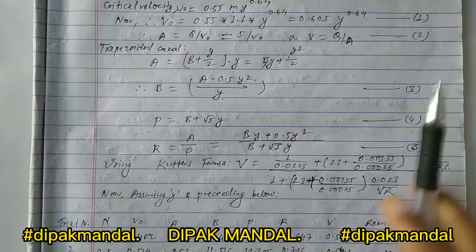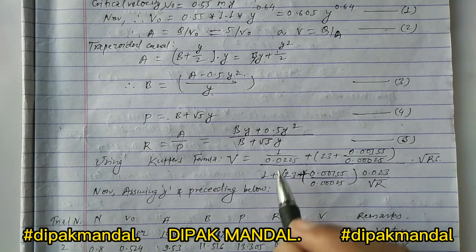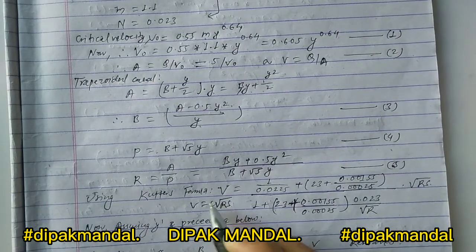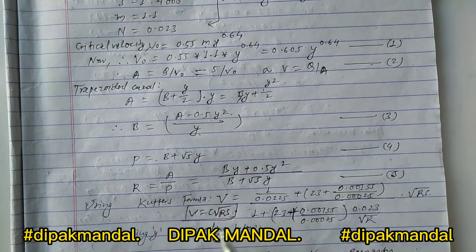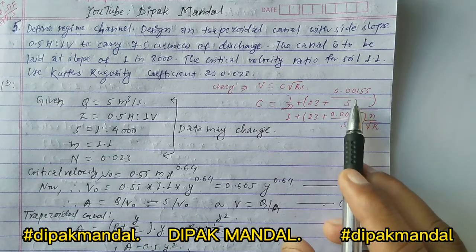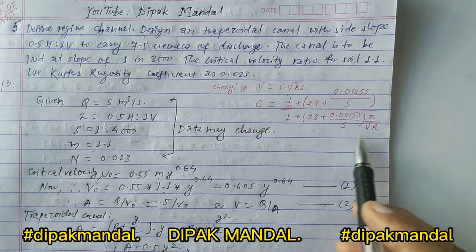So we have basically 5 different equations. Now we have to use the formula given by Kutter. V equal to C root over RS, this is the formula given by Kutter, and the value of C equals (1 by n plus 23 plus 0.00155 by S) divided by (1 plus (23 plus 0.00155 by S) into n by root over R).